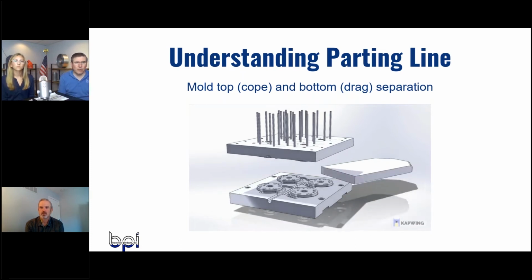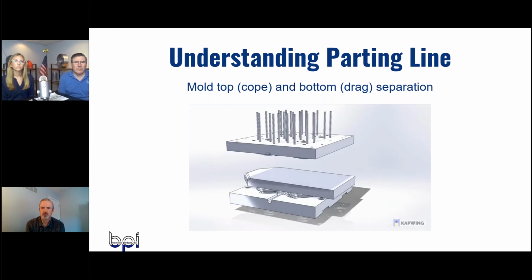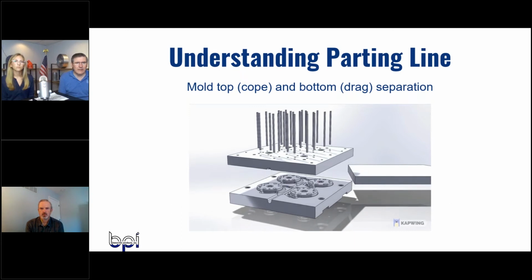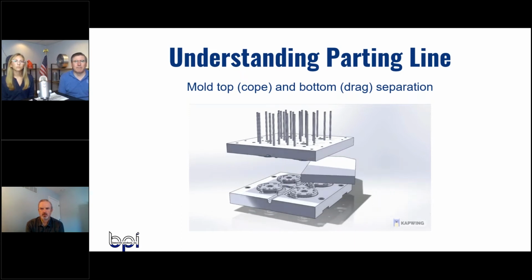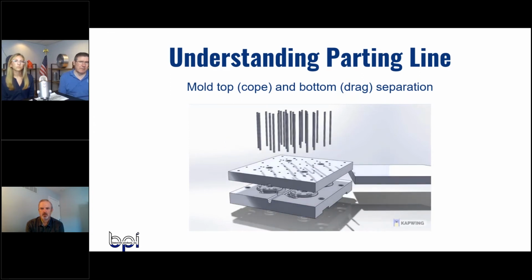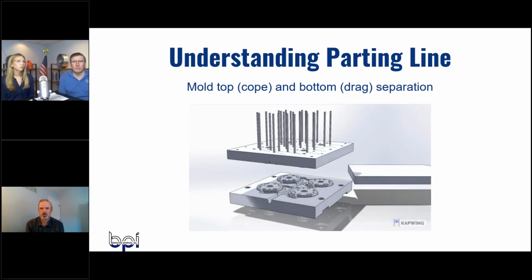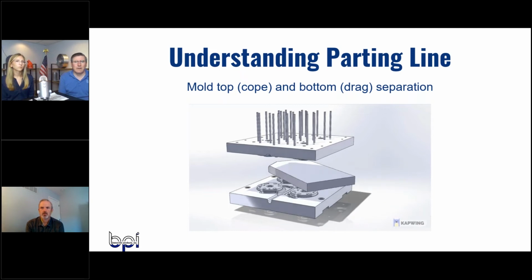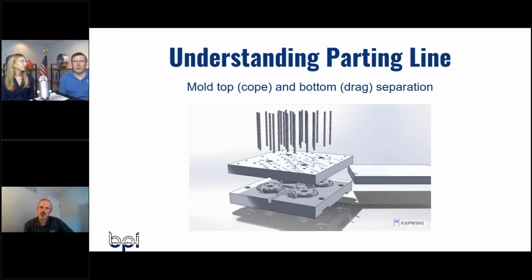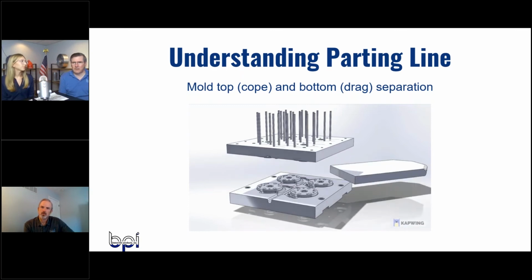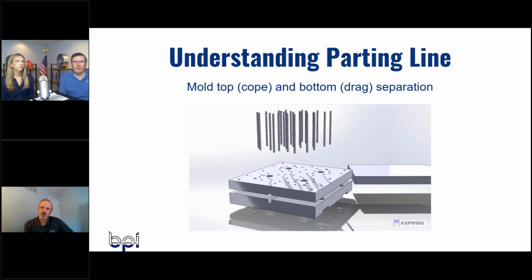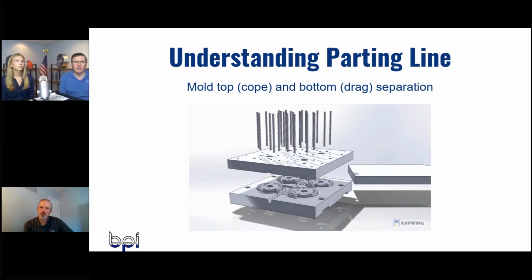If you have a really thin walled part, we can cast it thicker to obtain sound material in that area, and then machine it to your final requirements. There are some practical limits as to how thin you can machine materials too. The other thing to keep in mind is that you want to avoid big section thickness variations, especially with the thinnest castings. You want to make sure that you have gradual transitions in the part.